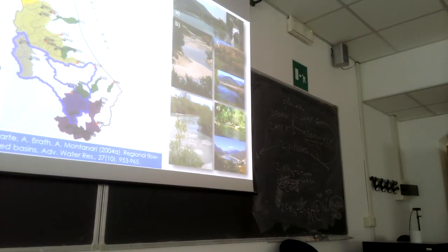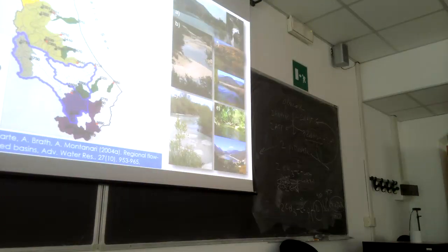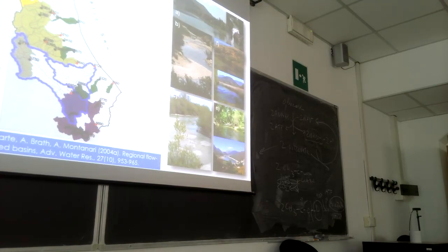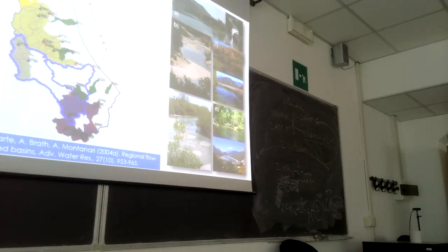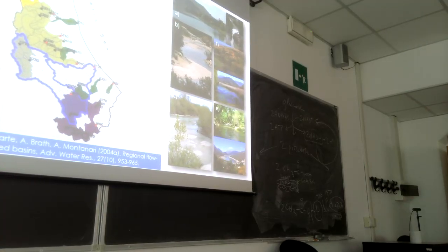You know what karst phenomena is? Really fractures that are opened by acidic rainfall events. So you have tunnels, very high permeability, and even some part of the water flows in natural channels underground instead of on the surface. So very different permeability from north to south.